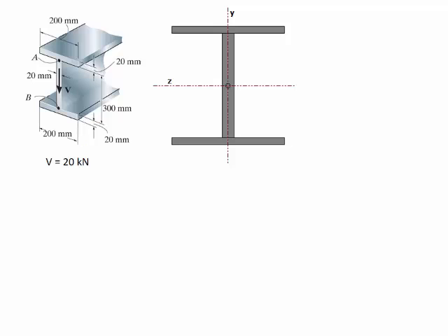And we are also asked to determine what would be the percentage of that shear force of 20 kilonewtons that is taken only by the web. So that shear force will be resisted by the flanges and the web, and we are asked to calculate the portion of the load that is taken just only by the web.